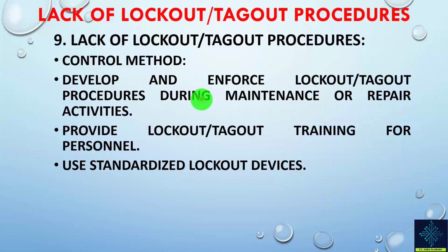We might also record some special video for this. Provide lockout tagout training for personnel, and use standardized lockout devices so that the indications are common to people and no misconception or any confusion happens.